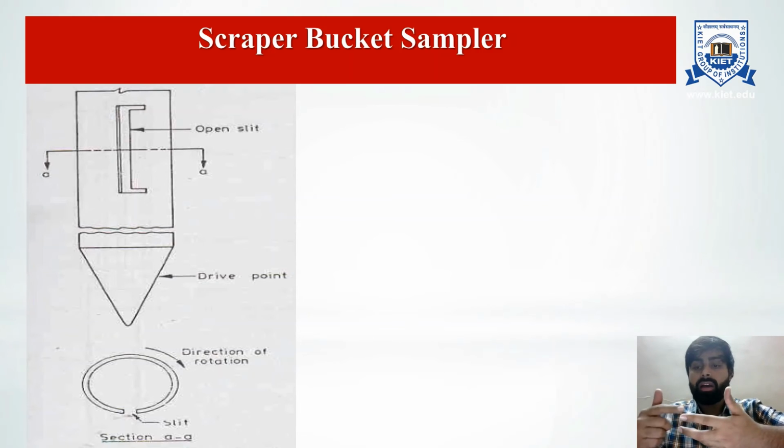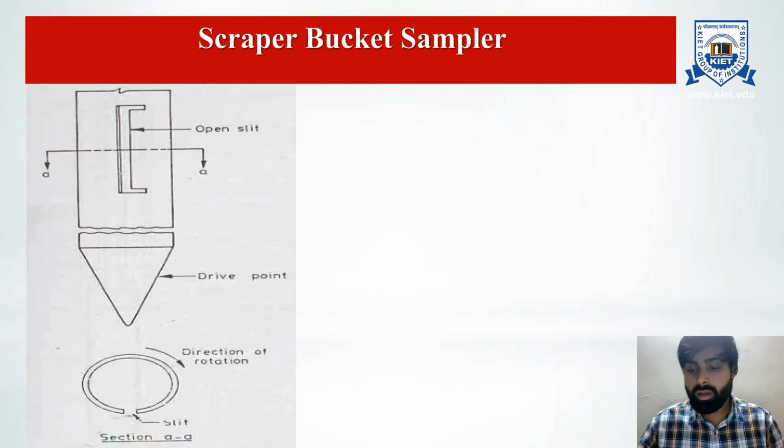The pebbles come in between the spring core catcher, and the spring core catcher remains open like this, and the soil leaves from this space. From the opening, the soil leaves out. To encounter this problem, we use the scraper bucket sampler.